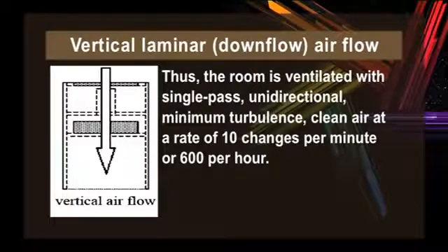Thus, the room is ventilated with single pass, unidirectional, minimum turbulence clean air at a rate of 10 changes per minute, or 600 per hour.